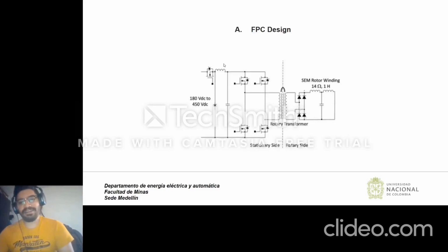This image shows the converter, which is digitally controlled by a slave processor to the traction engine. The traction controller issues the current field commands to the FPC processor through a serial peripheral interface, SPI. The FPC reports the current and health status of the estimated field on the same SPI bus.